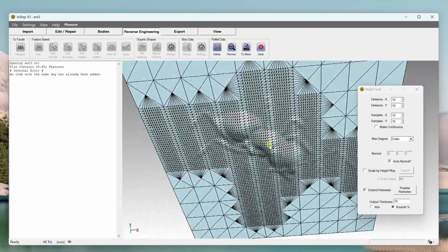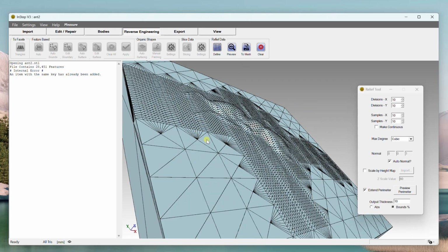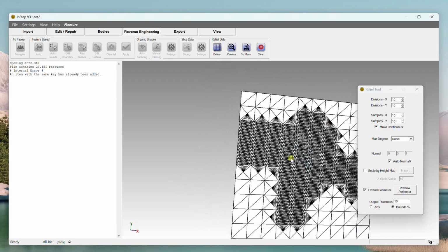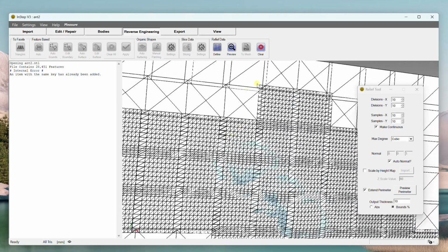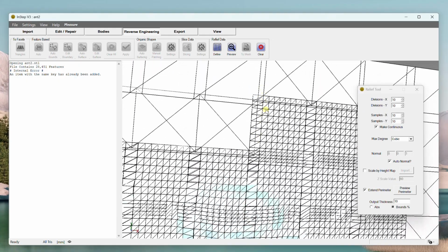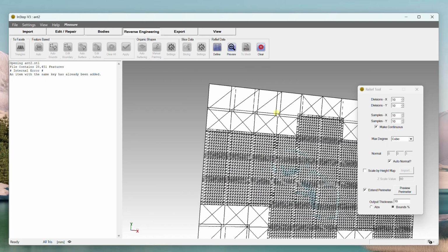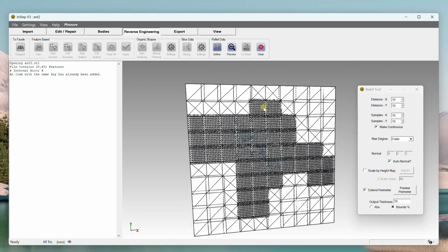If we like this and we want to just use it as a regular STL file, for example, let's say we do some carving or something and we want it to have this more uniform, we can click this generate to mesh, and that will generate the actual body as a set of facets. If we turn on continuous, I'll show what this does in terms of the overlaps here. It generates facets that aren't unique in their edges. It's just a patch per surface. So we can't turn that into a mesh. There's far too many sections that just won't match up. It won't do anything useful.